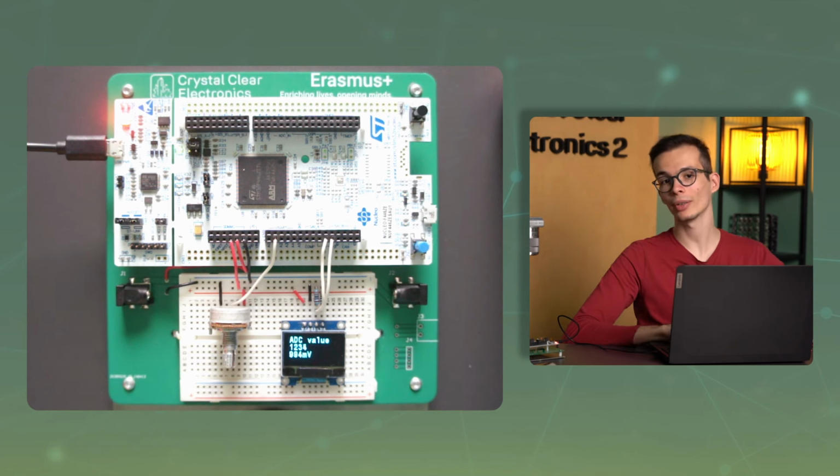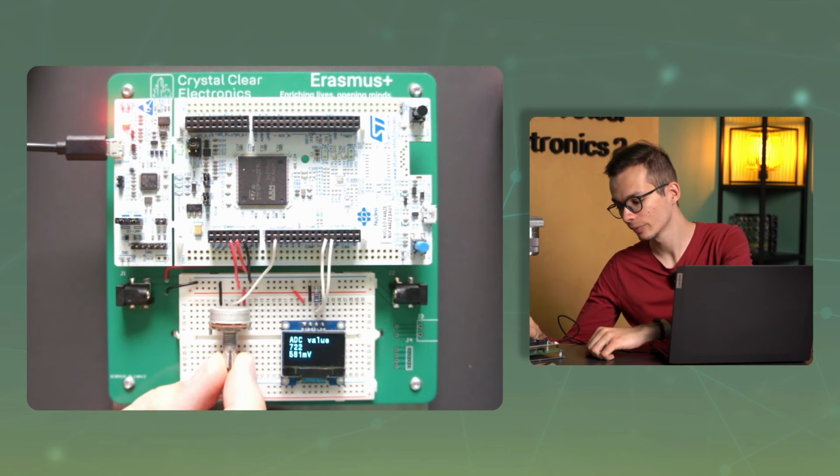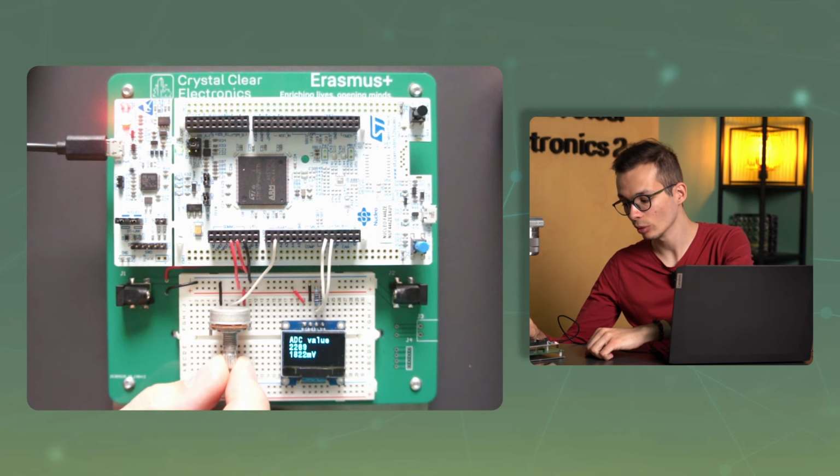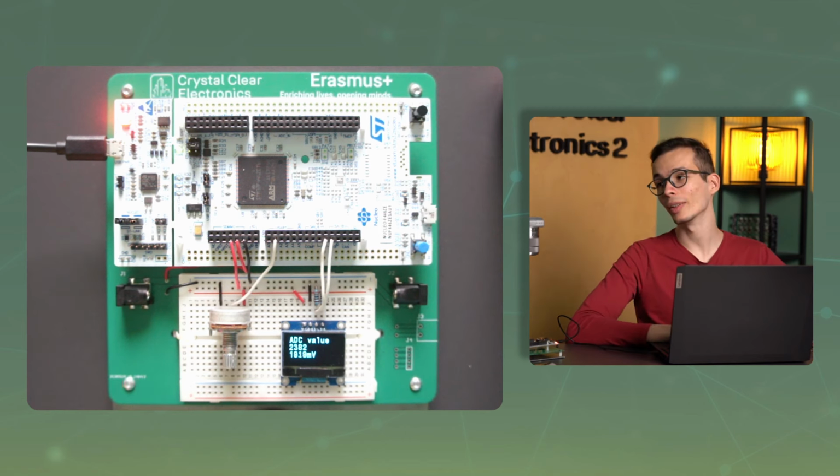As you turn the potentiometer, the value changes. Let's try it out. You can see that if I turn the potentiometer to the left, the value decreases, and if I turn the potentiometer to the right, the value increases. But don't think we are done with this. The program just presented, while simple, has a significant drawback. The microcontroller waits for the ADC to complete its measurement.